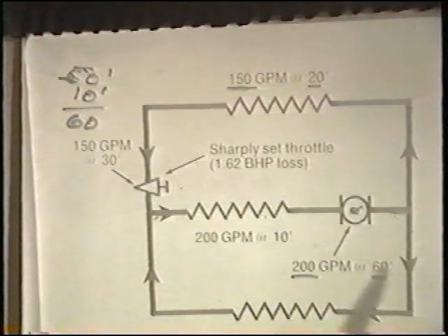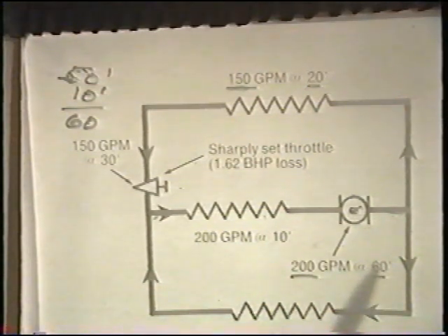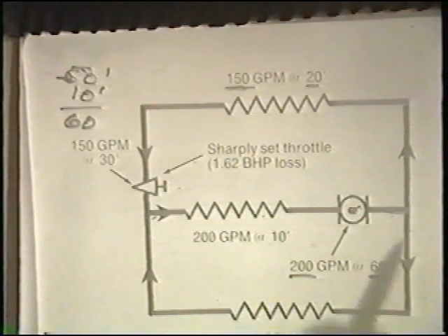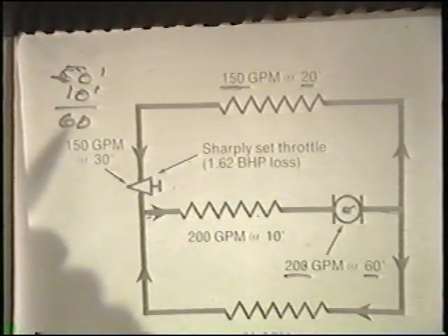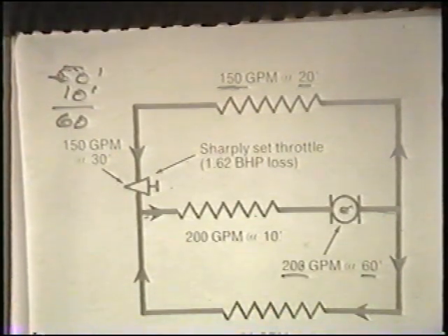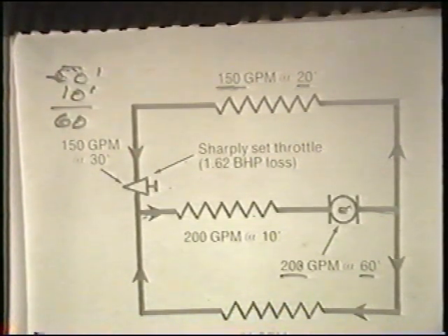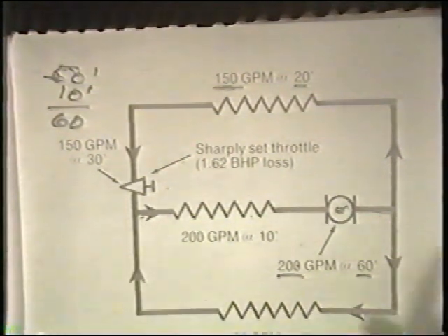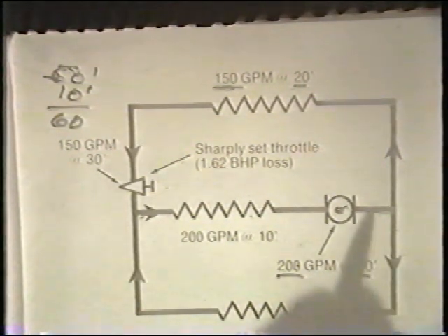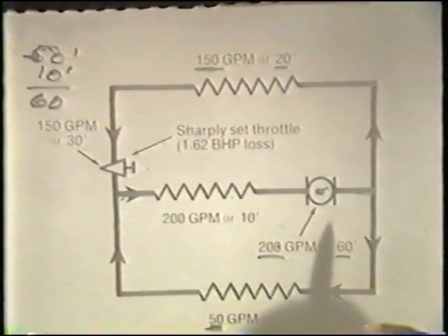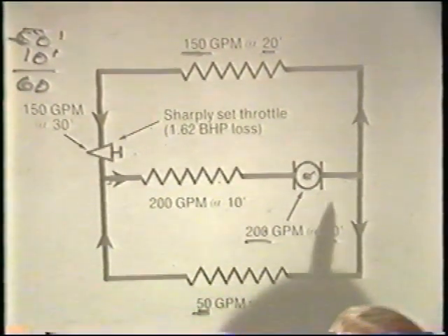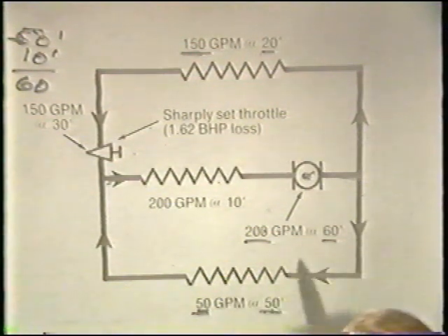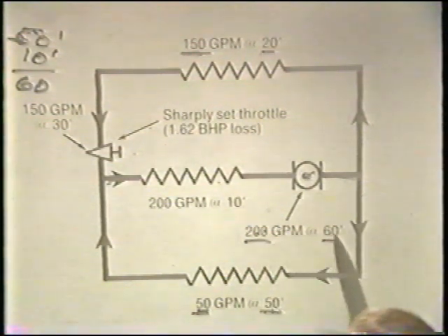Now we can equate through the basic pump energy power relationship that flow and head are the predominant factors in terms of establishing pump power draw. So in this circumstance, we can take flow times head and establish a number that is truly relevant to power consumption for this system. So we have 200 gallons per minute times 60 feet.